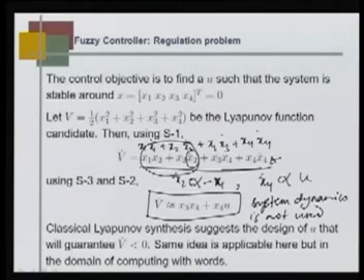So, x4 is theta dot and x3 is theta, which is very simple. And we also used two other relations from the systemic connections. We know already the acceleration of the pendulum is proportional to the input, and x2 dot is proportional to minus x1 just by constructional feature. So, using these two rules we found V dot to be qualitatively x3 x4 plus x4 into u.